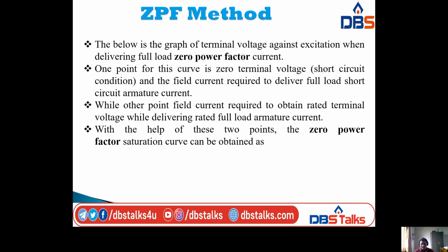The other point is the field current required to obtain rated terminal voltage while delivering rated full load armature current. This is one more point. With the help of these two points, the zero power factor saturation curve can be obtained as follows.